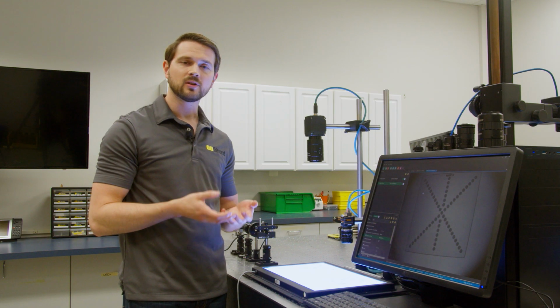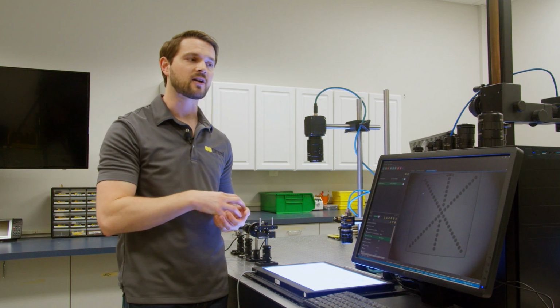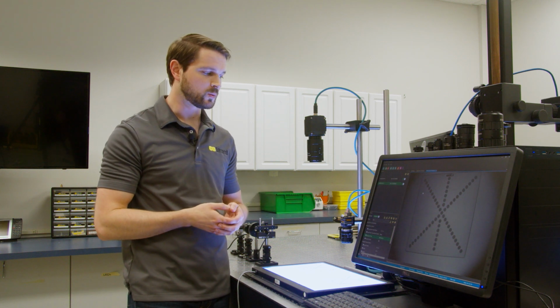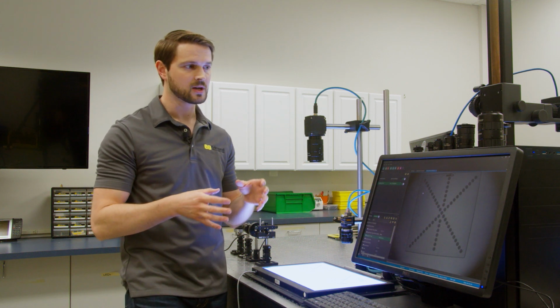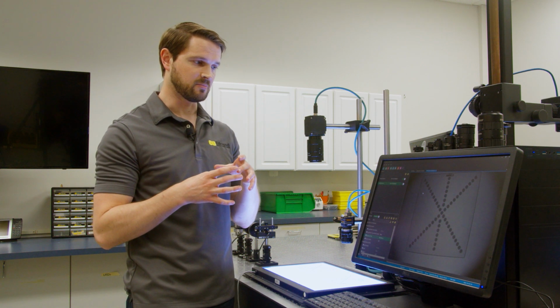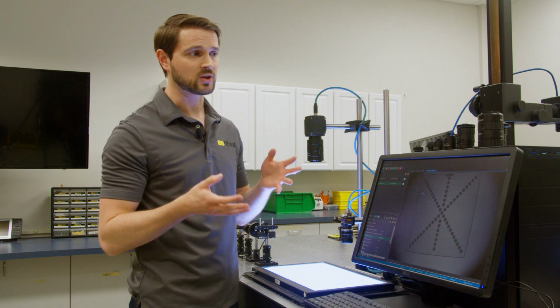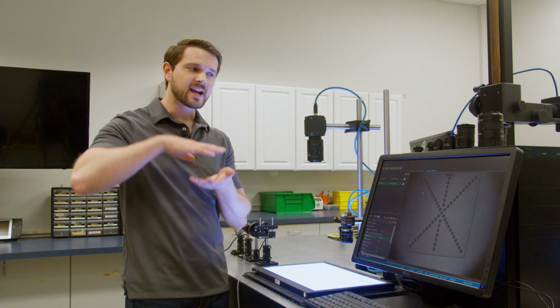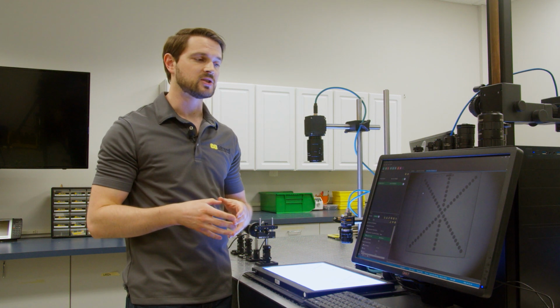And what we can see if we look at a plot like that is just how much that brightness tends to tail off. And so in most cases, you probably wouldn't want to use this particular lens on this particular sensor because, again, you see those dark corners. But there are some instances where you might want to. Let's say you're looking at a bottle cap or something that's round. And so you don't necessarily need to have the corners in view, but you need that extra height and a little bit of extra width in order to see the full image there.